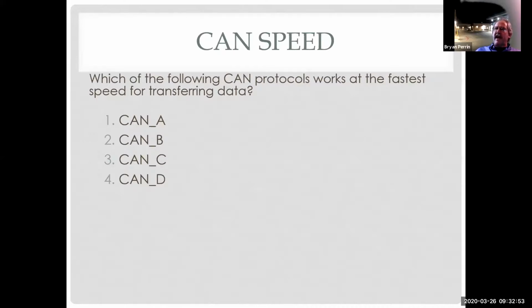It comes down to addressing. So your scan tool is basically an address book. The address book is limited on who it knows is there. It can only talk to who it knows. So if it wasn't programmed to know someone's there, it's not going to talk to them. And then it's also limited on which network it can talk on.